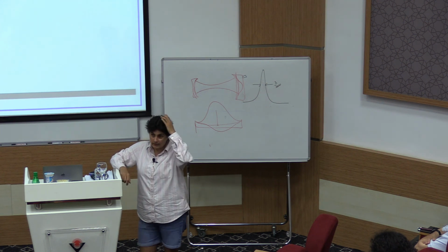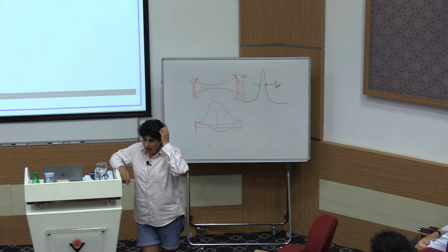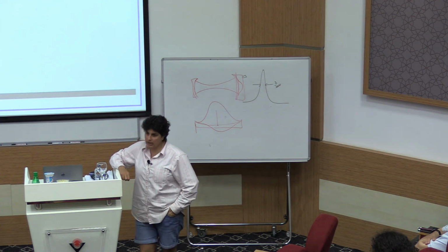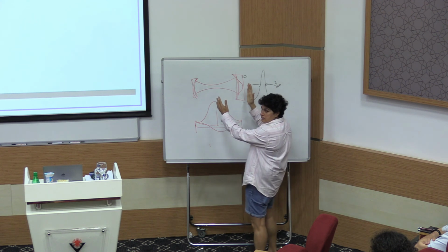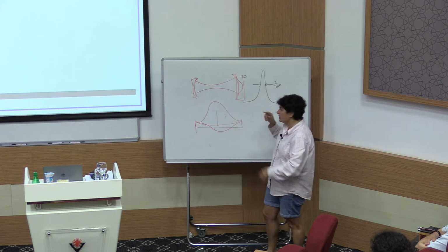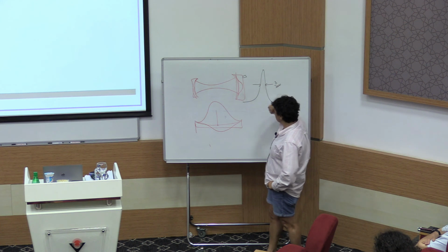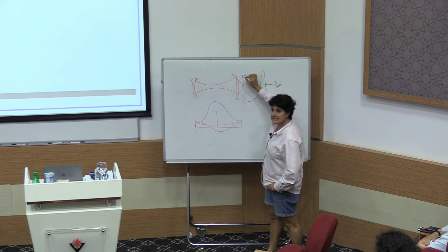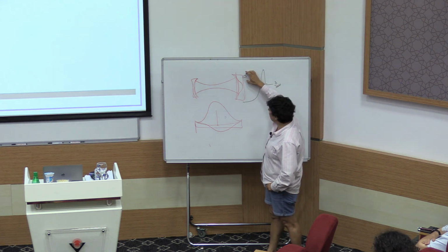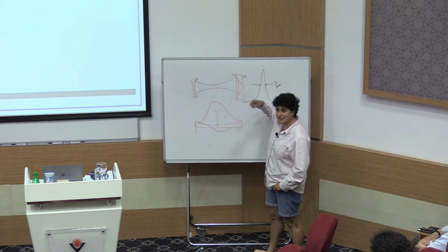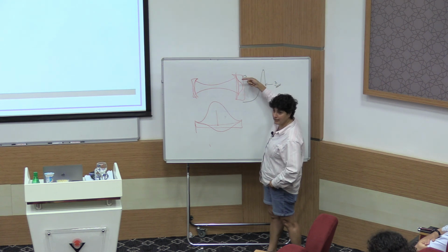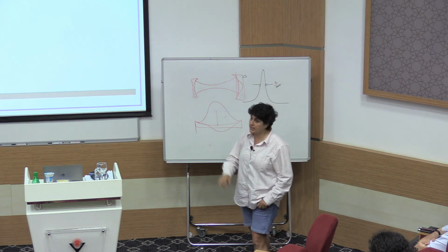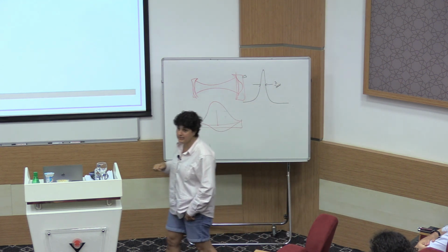As an output, not for measuring. For the output, yeah. That's a fine question too. Again, in the case of the mirror, say I'm trying to control the mirror position because I want it to be within this fringe. These mirrors have little magnets attached to them, and the magnets are sitting inside voice coils, just a little coil. Then we can drive current through the coil to make a magnetic force and push on the mirror. So that's one example, again, of many, many different ones.